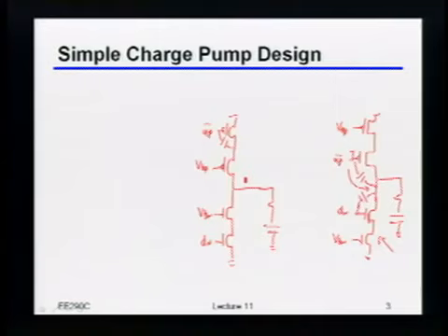But what else happens when you turn a switch? Ah, there we go, charge injection, right? So here, for this switch, looking down, all it sees is the parasitic cap and maybe the output impedance of this current source, right? Looking up, it sees this big loop filter. That loop filter probably has lower impedance, right? So most of the charge from that switch is going to go into the loop filter, right?